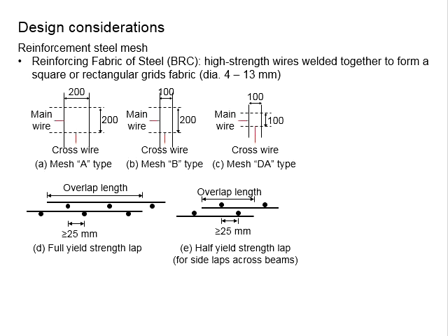It is only that this BRC is more rigid in terms of the spacing of the reinforcement bar, which is either 200 or 100. But if you choose to have the reinforcement bar laid and tied together in a mesh for the slab, then you can have all sorts of spacing, something like 225, 250, 275, 350, even 400.